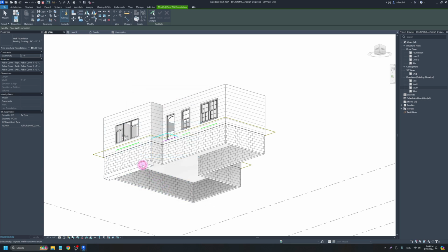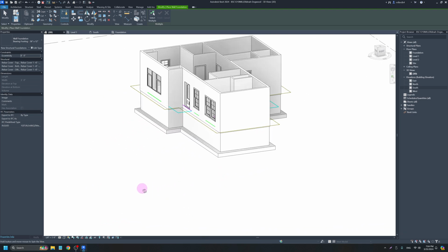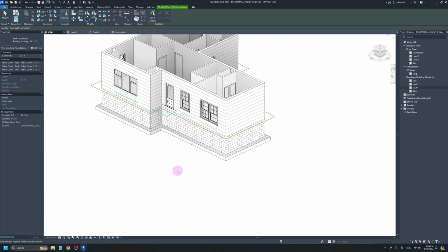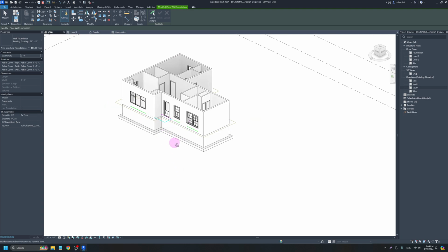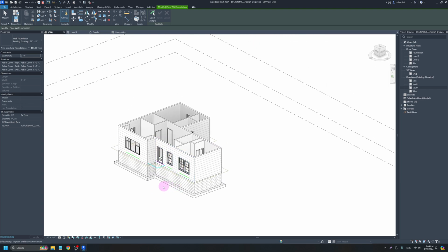And this is one where you are just clicking underneath, but you can also, by Control Z, hover over one, hit tab, and then click once, and it'll put a footing around all of that foundation wall for you. So I've got my foundation here. We're going to, just because it's our first Revit project, not put any site on the building at all. And we are almost done for this video.